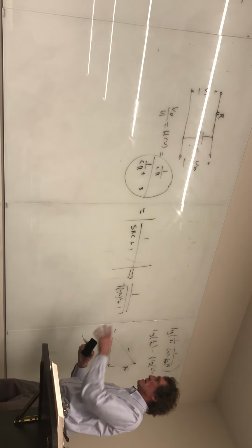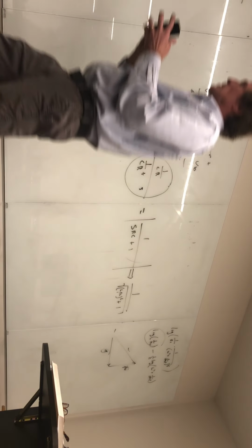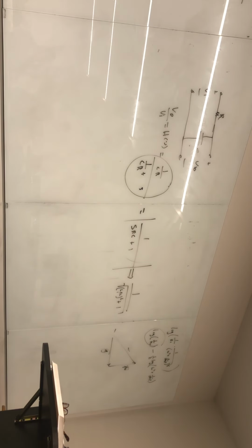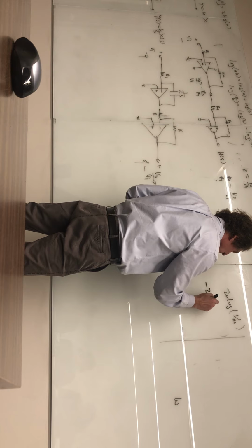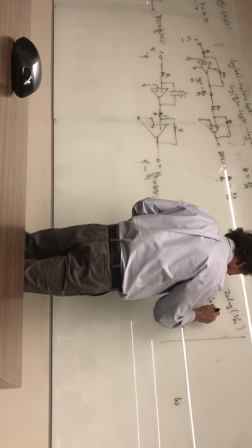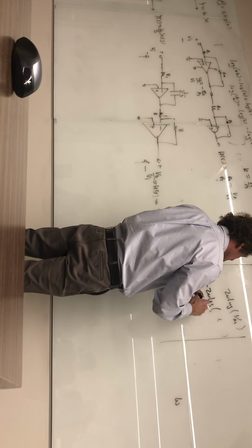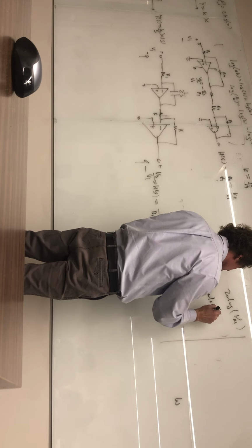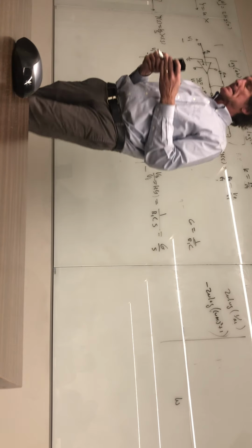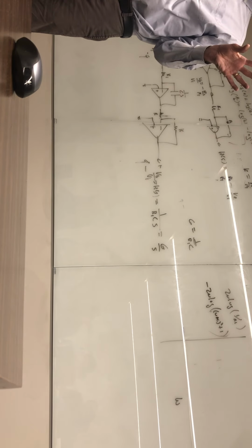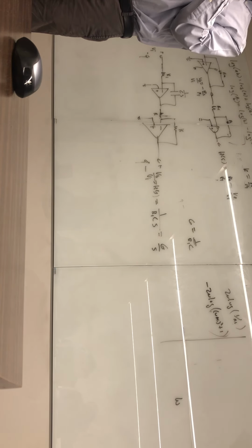Now we're going to plot. I've got that, and I have this term here. So when I put it on this axis, just follow me now. That's fine. Follow me? Now I'm going to have minus 20 times the log of the quantity (omega times RC) squared plus 1. All right? I don't mean to be so sloppy, but do you all see what I've done here?